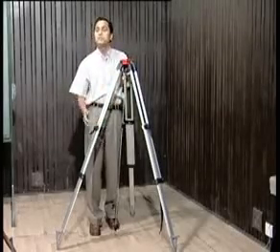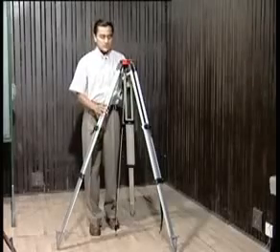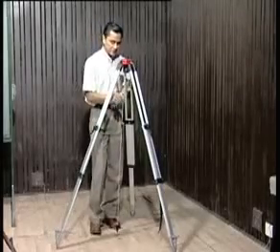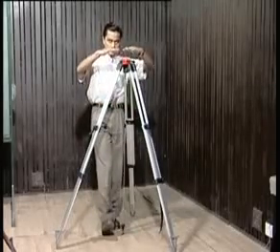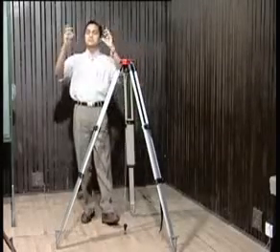instead of giving it a radial movement. So you can do that. So finally what we will achieve is our tripod is approximately leveled. It's eye judgment. Just by eye judgment you can ensure it.